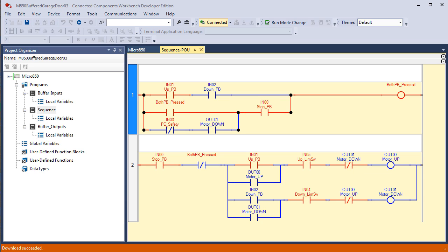There, I'm pushing the up button, see nothing's happening. If I push the stop button, then the up button, now you see it's going up. And if I change the state of input 3 in the top rung, nothing happens because the motor's not going down, it's going up. This logic works really well. So what we have now is we have safeties, so the operators can't monkey around with the up and the down push buttons. If they happen to do both of them simultaneously, the whole thing's going to stop until they push the stop push button to reset it.